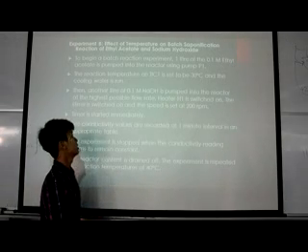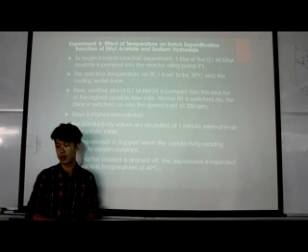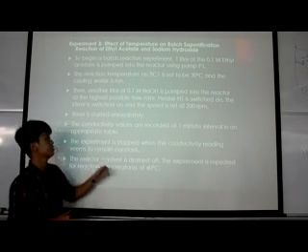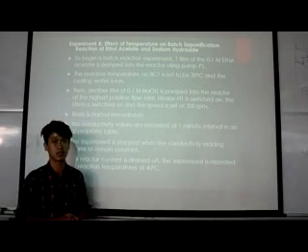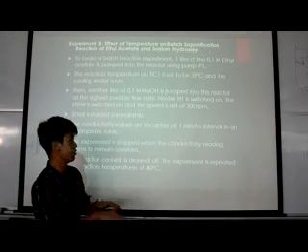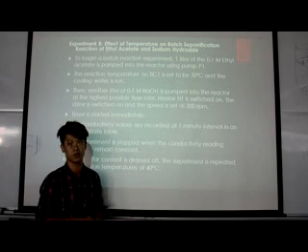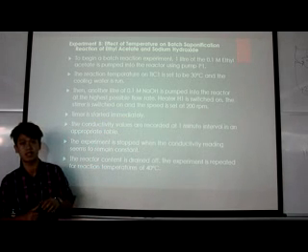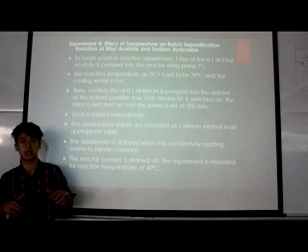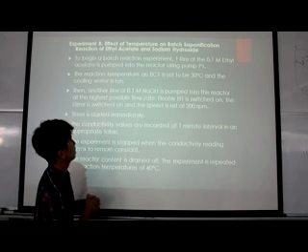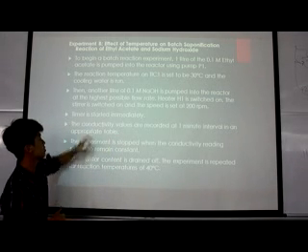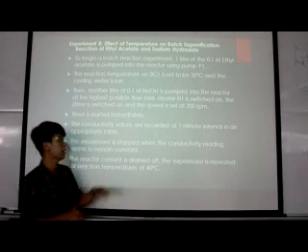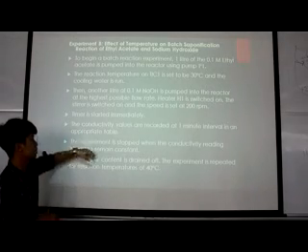Now, moving on, this is how we carry out the experiments. First, to begin our reactions we have to pump the reactants inside the reactor, and the temperature will be set to 30 degrees Celsius, because we have to compare the reaction between 30 degrees Celsius and 40 degrees Celsius. So now, another liter of the 0.1 mole sodium hydroxide will be pumped inside the reactor as well. Then we will start the reaction between the sodium hydroxide and the hydrochloric acid. The moment you start the experiment, the timer is started immediately, and after 1 minute intervals, we will record the data inside a table.